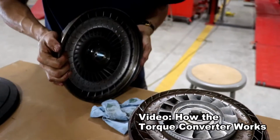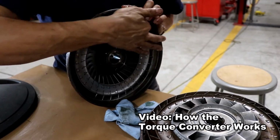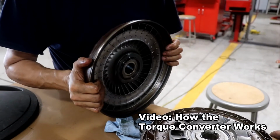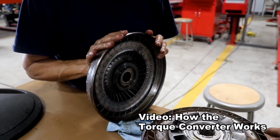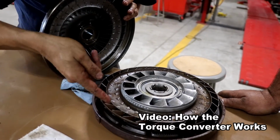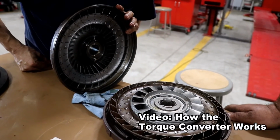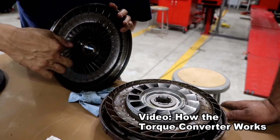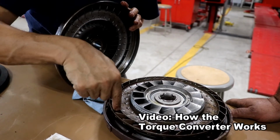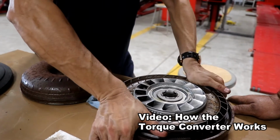What happens if the fluid comes out through this? The name of this turbine is the pump, because it pumps the oil. This one is spinning at high speed. The oil enters over there at high speed and high pressure and returns through the middle into the oil pan. What happens if the speed of this element increases a lot? The fluid enters here at high speed and high pressure, and suddenly this element engages with this.